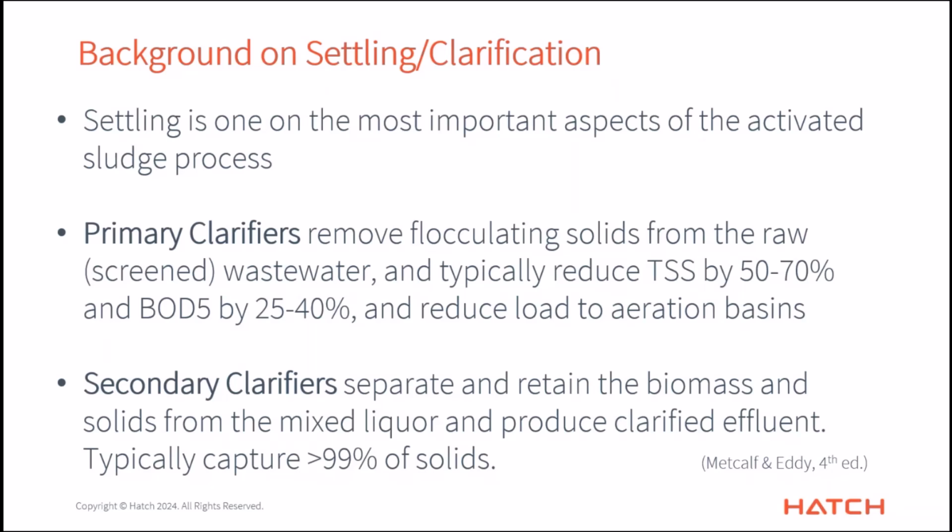Now, the secondary clarifiers, as you know, are there for a different purpose, and that's to separate out and retain that precious biomass that we've been growing in the bioreactors and bring that back as part of the mixed liquor. And by doing that, you're producing some clarified, hopefully very clean effluent that can go onwards and get disinfected and then head out to your receiving water body. And so those are designed, instead of talking about a TSS removal of 70%, we're talking more about, in this case of secondary clarifiers, capturing almost as much as you can.